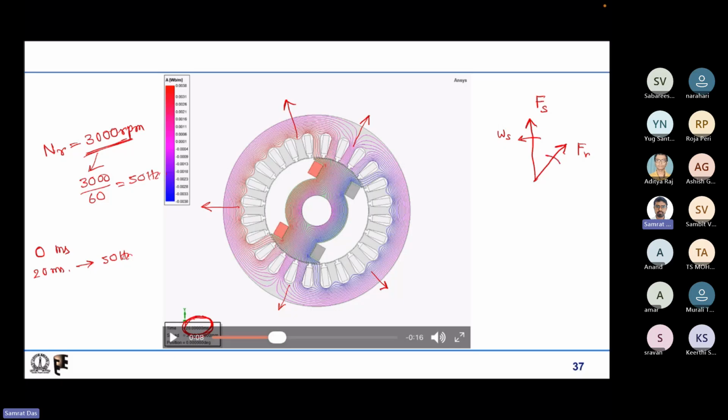That is why the second magnetic field is also rotating at the same speed as the rotor speed, omega r, which is equal to the speed of the rotating magnetic field. So this is how we can create two magnetic fields which are stationary with respect to each other, and there is some angle in between. You can see that this is the simplest of machines, which is known as the synchronous machine, simplest to realize.